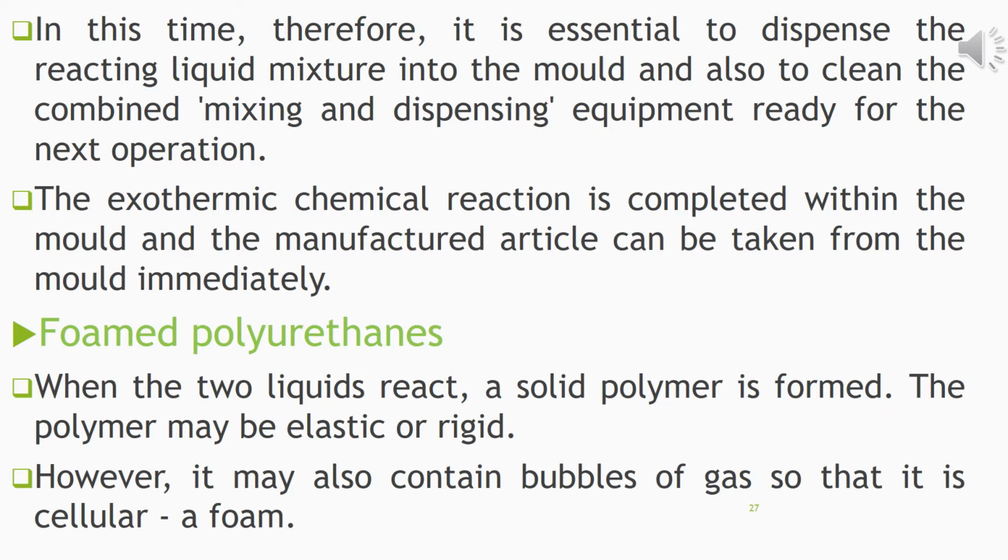So it is essential, at that time, to dispense the reacting liquid mixture into the mold, and to clean the combined mixing and dispensing equipment so that it is ready for the next operation. The exothermic chemical reaction is completed within the mold, and the manufactured article can be taken from the mold immediately. The heat goes out, and the article is formed immediately.